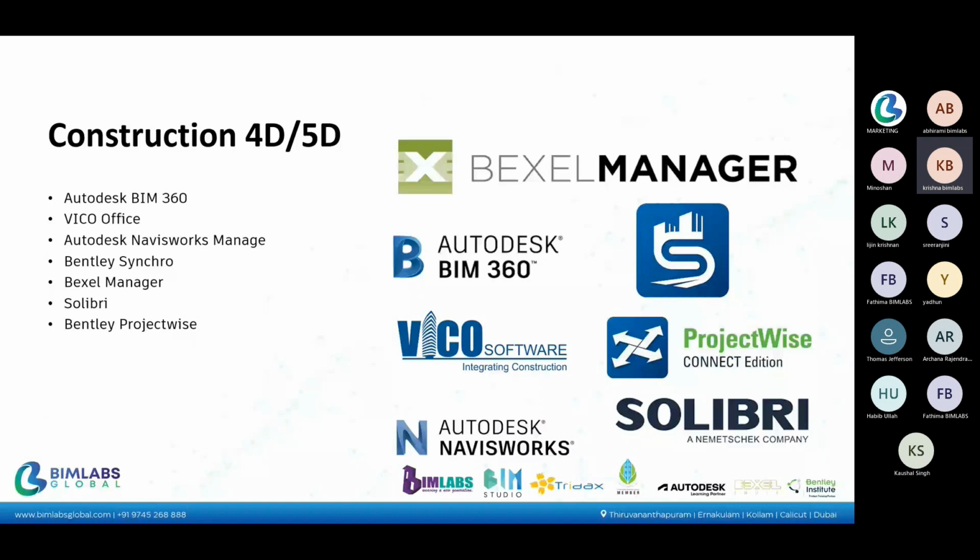If we are a team, and in my model some elements like walls are to be maintained by one team member, and doors and windows by another team member, then I can create worksets. I can create different worksets like walls, doors, and windows, and assign them to my team members, so that the particular team member who got that work can work on it. That is BIM 360 work sharing, which we can do on a cloud platform.